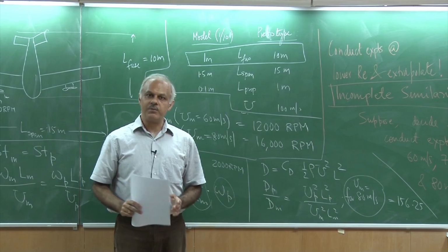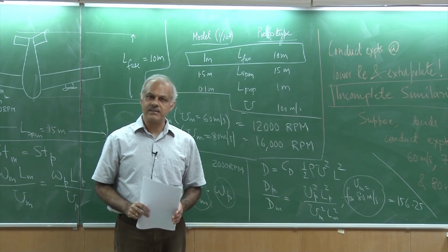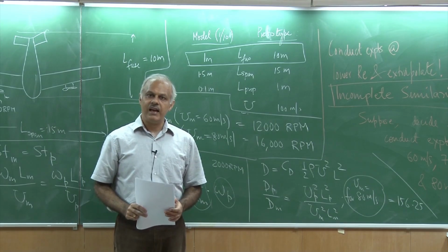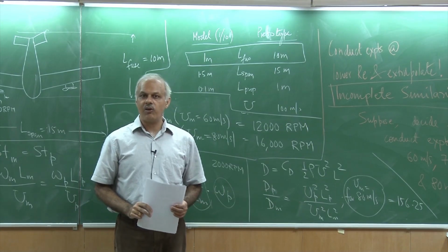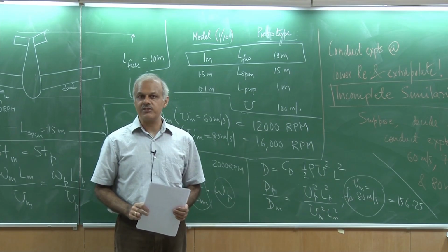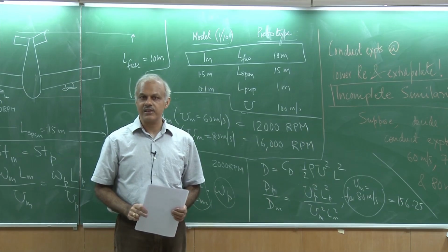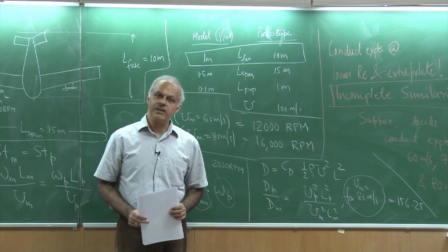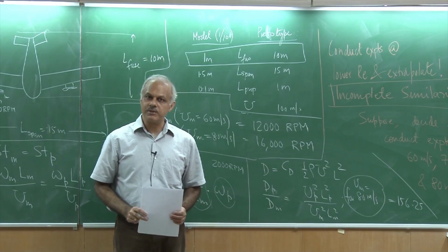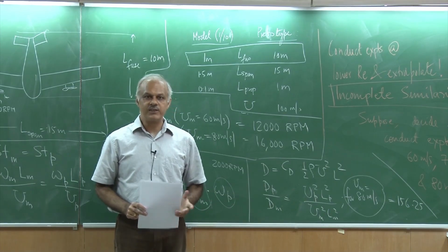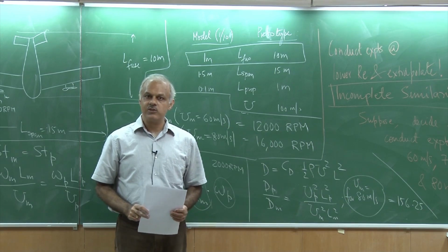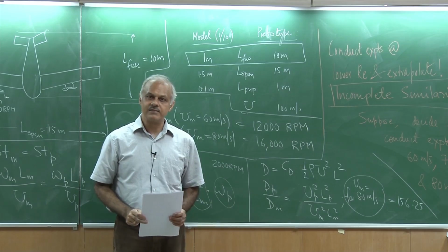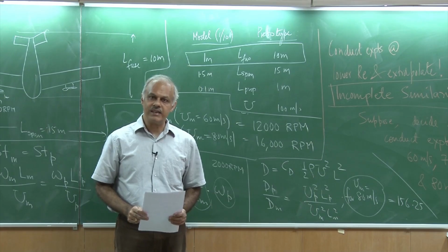For example, if Reynolds number is important, it should be matched, Euler number should be matched, and the outcome would be that all the dependent quantities like the drag coefficients and so on will match. Then I presented you with an example where this matching is not possible, and we have to come up with our experience, with our creativity to still model the problem despite the matching not taking place. So we will send you some practice problems, hope you take a go at them and understand this a little bit better. Thank you.